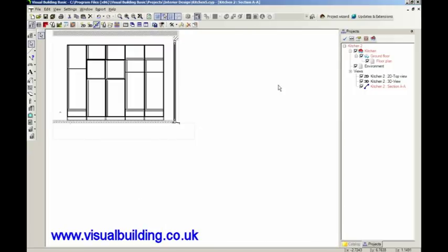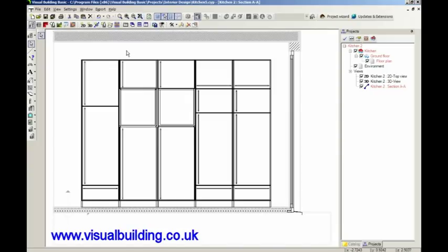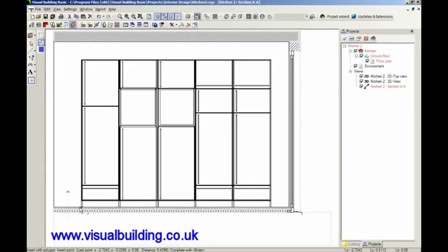And let me zoom through here. I can now use the surface editor tool to actually create a surface surrounding my kitchen. So I've selected the polygon settings, so I can now just draw my polygon of the solid that I want to create around my kitchen units. Just clicking on each point, then right click, complete to enter.